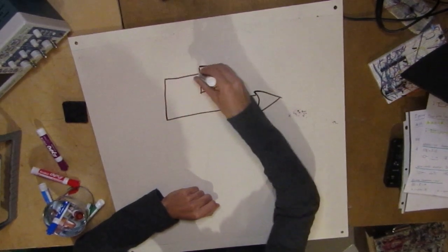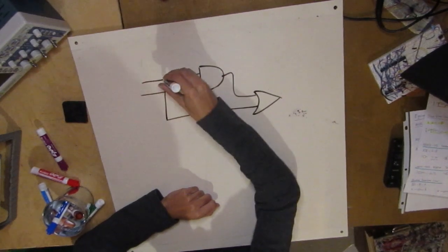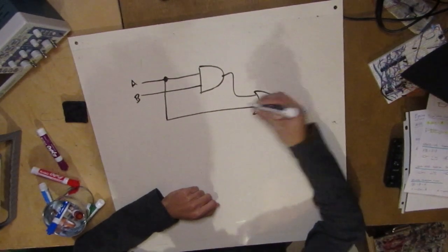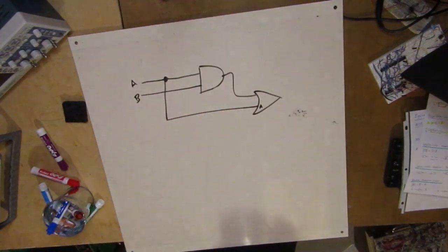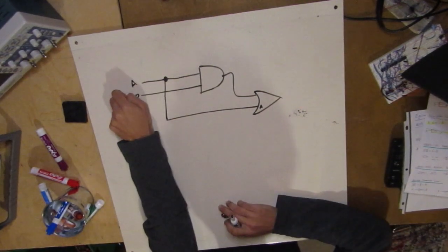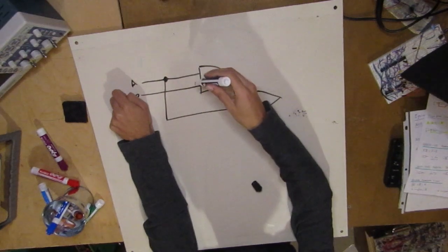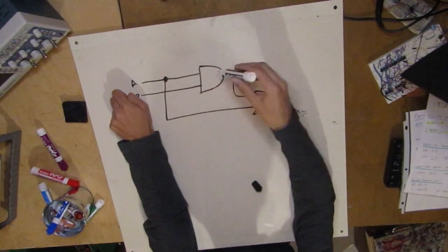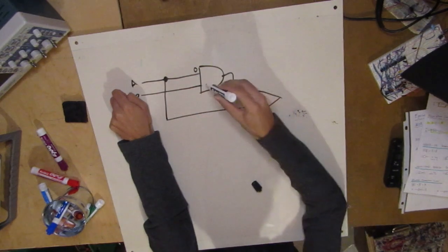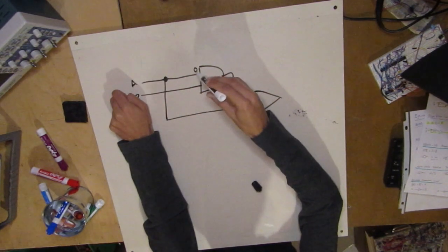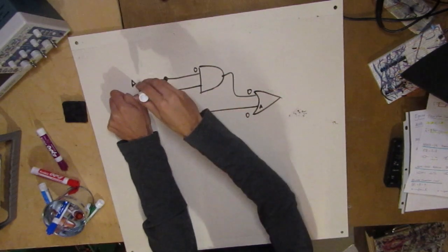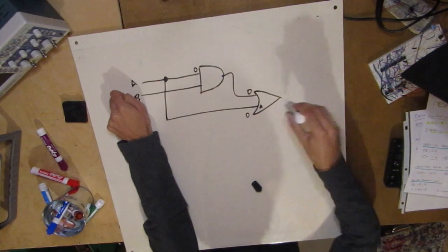And this guy is going to be coming like that. You label this as A, label this as B. And this is the chain that's coming in for the A. Okay, let's forget about B. Pretend A is a 0. So we have a 0 here, and also a 0 here. Now the AND logic tells us, okay, even if at least one of them is 0, we're going to get the 0 on the output. So A was originally 0, so the 0 is automatically transferred.